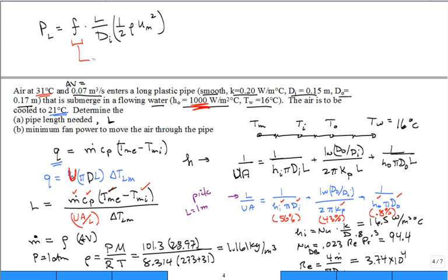You look it up as a function of Reynolds number off of the Moody diagram, or you can use the equation 0.79 natural log of the Reynolds number minus 1.64, all of that to the negative 2 power, and that friction factor comes in at 0.0224 using the equation, which agrees if you do it visually off of the Moody diagram. We calculate the pressure loss to be around 28.1 Pascals, newtons per meter squared.